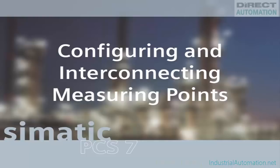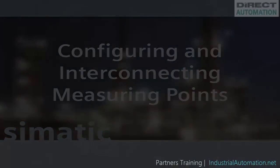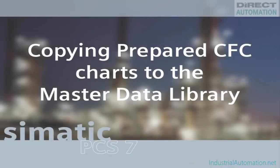In addition to these sample solutions, which are created in the form of CFC charts, a sequential control program in the form of an SFC chart is also used. The SIMATIC PCS7 library comes with standard templates, for example for motors, valves, and controllers. For the purposes of this exercise, we will make use of a customized library to show you how you can use your own company-specific templates. In the following steps, this library will be de-archived using the SIMATIC Manager.